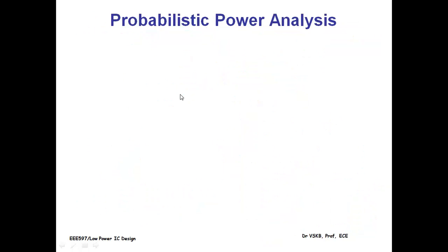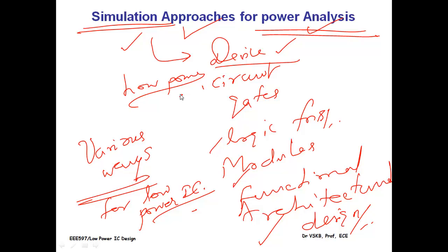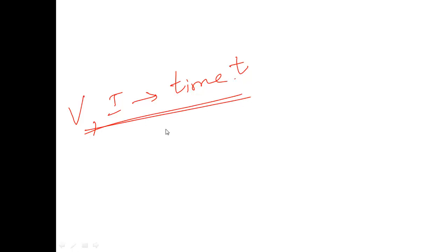Simply said, your PSpice or your Cadence Spice, Spectre Spice, they normally consider the voltage across any component at the two terminals of the device, the current through any loop you have, and you go for simulating that over a particular time t. And this idea is helping you to identify how the particular limb, the edge of your circuit, is working. The edge is, what I mean is the component between two terminals, between two nodes, naturally. And when I have some billions of transistors in one complete circuit, how am I able to go for identifying the I, the V, and with respect to the time also for various input conditions.